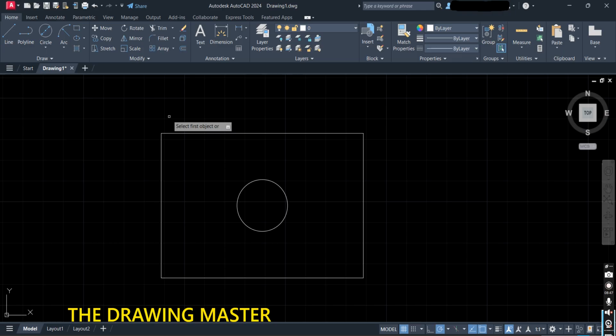Students face a problem with fillet here: when we are selecting the object, let's say select this one, many times your radius does not get applied. Why is the radius applying right now? Because I have already selected the value beforehand. This is the problem you will face: when you draw it, this will not work. It is working on my screen but may not on yours. So what do you have to do? First you have to select the fillet. Before selecting the object, first you have to type R, enter. You can see I had already selected 20 mm, that's why it was working.